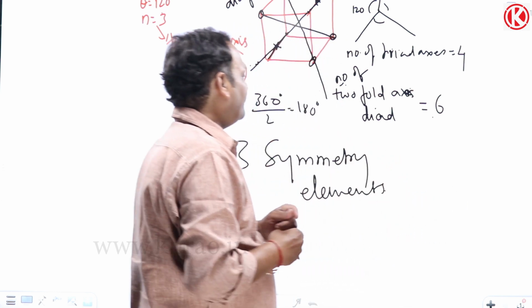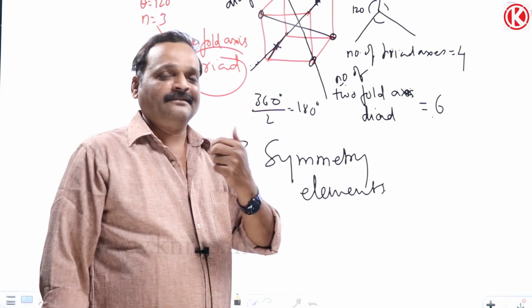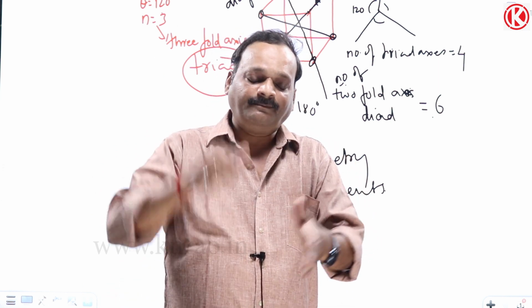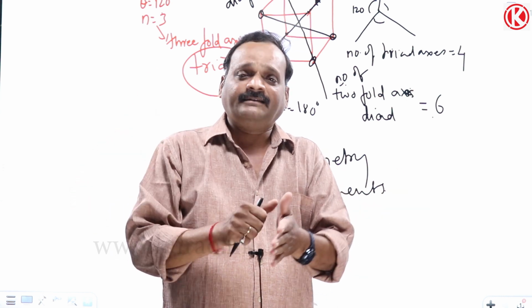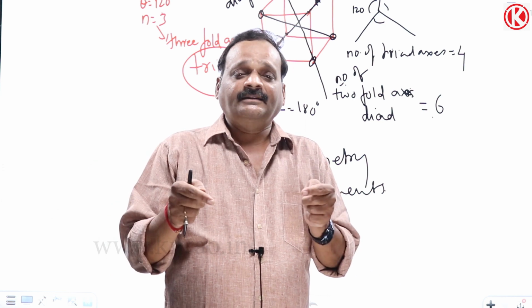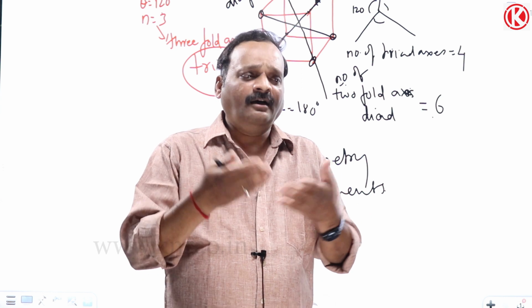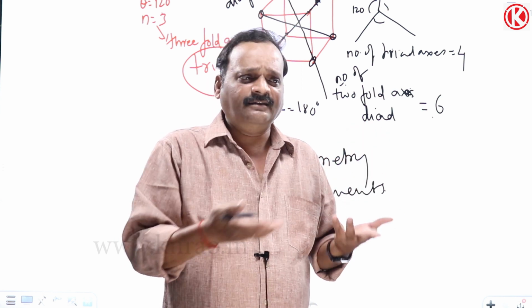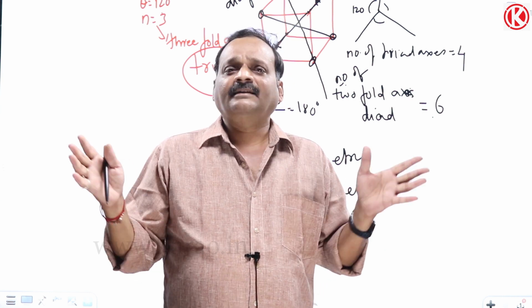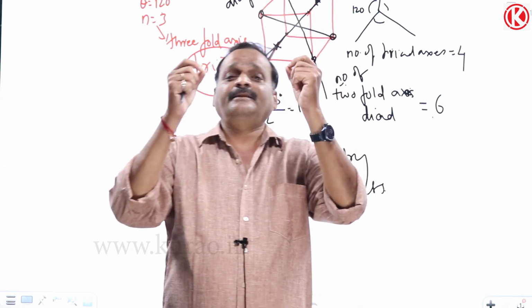Okay, right? Now what about this cubic system? Cubic system has center of inversion. Its body center itself is center of inversion. So you take any cubic crystal, you do whatever you want, you apply pressure in any direction like this, it will not show piezoelectric effect. No potential difference will come. Or if you apply potential difference, no mechanical compressions and extensions will be happening. So all cubic structures we have seen, silicon, germanium, diamond, etc., whatever you do, they are not useful as piezoelectric crystals. Only crystals which do not have center of inversion will behave as piezoelectric crystals.